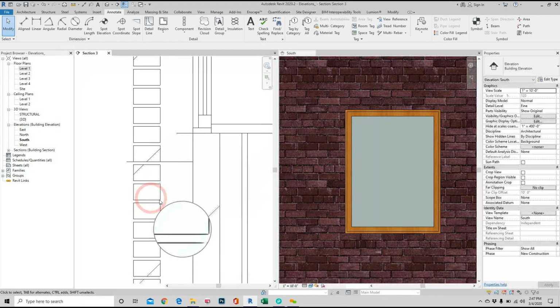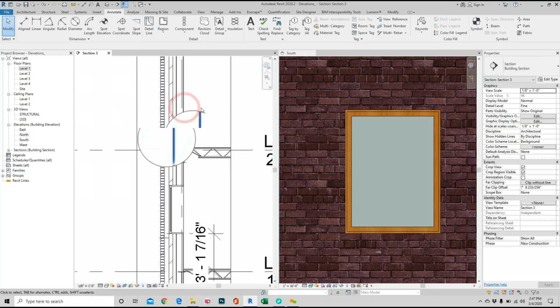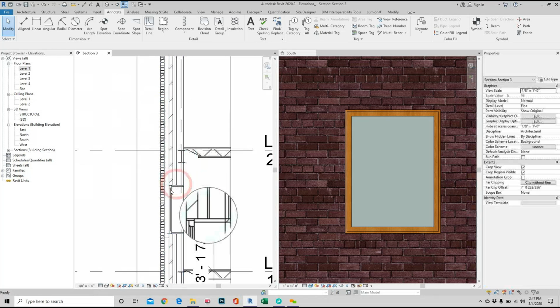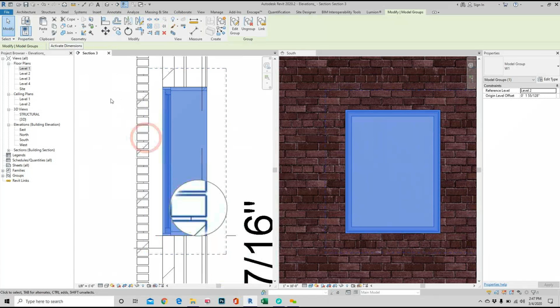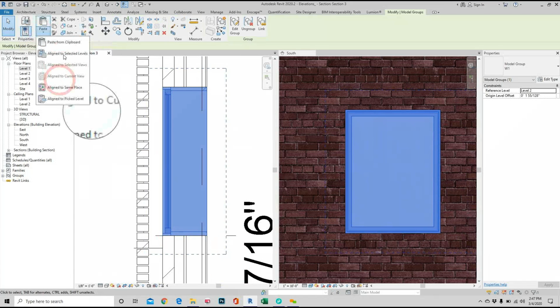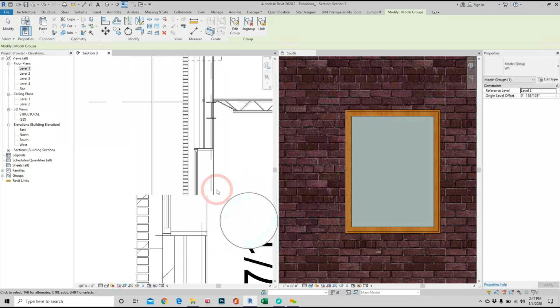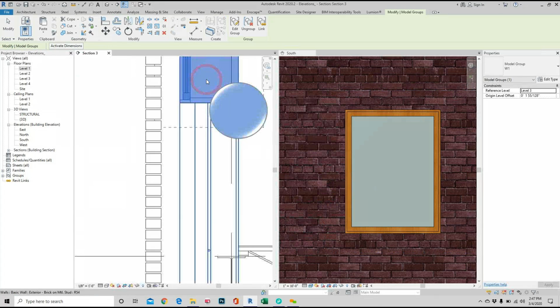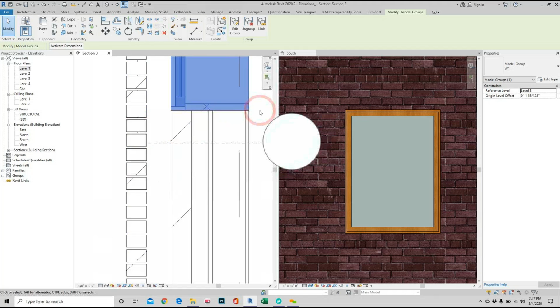All right. So now in here, I can go to my entire elevation and my windows and start creating things to course, to make sure. So I can go here, for example, copy this guy, press Ctrl and paste, align this to my 3rd level, and push that up to my 3rd level. And because I haven't changed the coursing, the lintel should fall where it's supposed to.